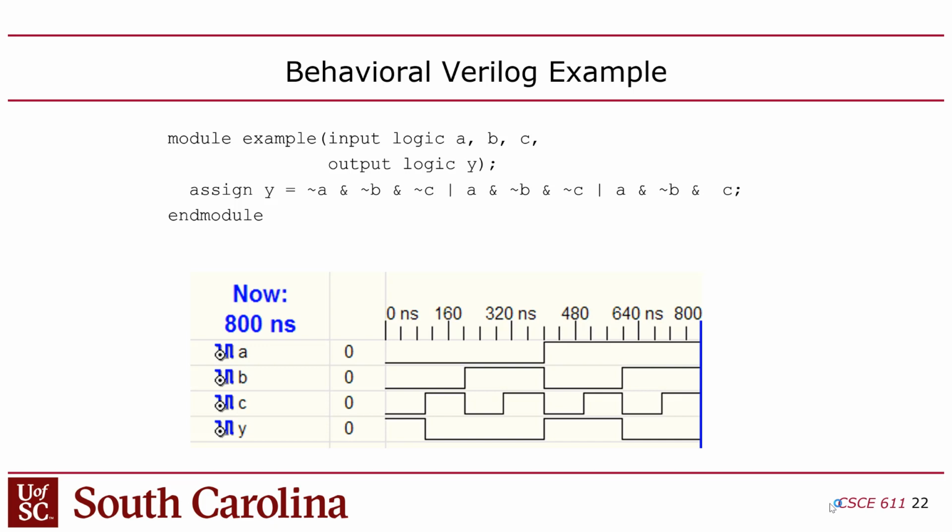You're generally going to see something like this. It's called a timing diagram, and it's meant to represent an oscilloscope. The other thing I want you to notice here is that whenever an input changes, that triggers a change in the output. For example, here I had all three inputs change simultaneously, which triggered Y. In this case, I had two changes that triggered Y to change. And in this case, only one. A, B, and C were 0, and all I had to do was bring C up to 1, and that caused a corresponding change in Y from 1 to 0, right?